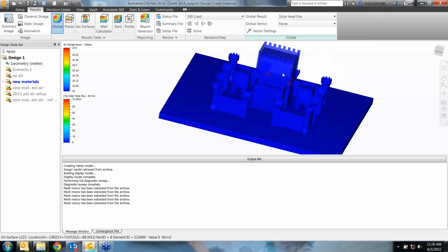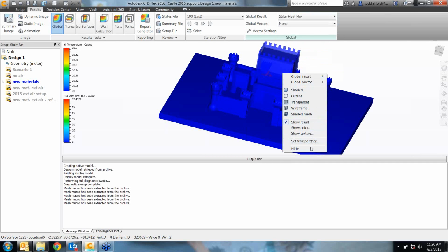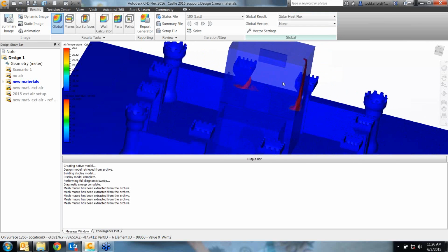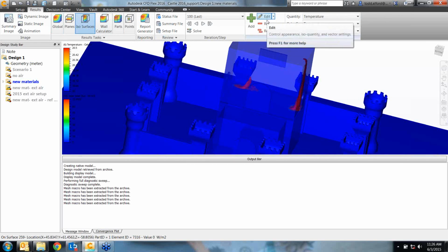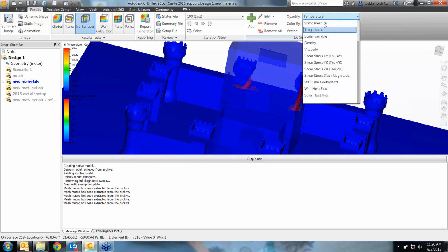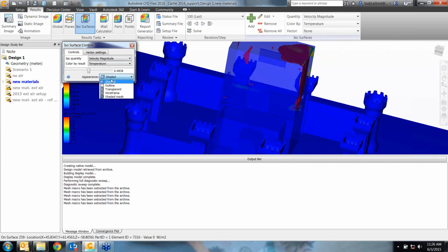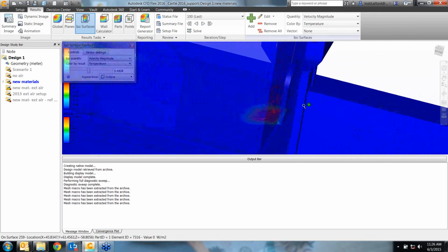to show better what the heat load might be. The best way to truly get the heat load shown on the exterior is to still have the dome. So it really just depends on what you need out of the analysis. I talked to some customers that just having it on the inside is enough, and then you can absolutely get rid of all the mesh for a dome. My dome is not appropriately sized, so you'll end up with a massive runtime. The larger it gets, the more elements you're going to use.